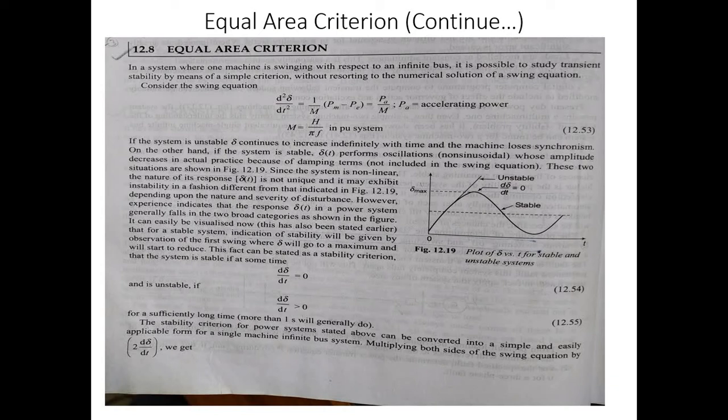It is the variation of rotor angle del with respect to time. That means it is the swing curve, but it is given for both conditions. The system is stable during the normal condition, whereas whenever the fault occurs, your system becomes unstable. So from the graph, it is clear that when del continuously goes on increasing, as shown by the straight line, then your system is unstable.